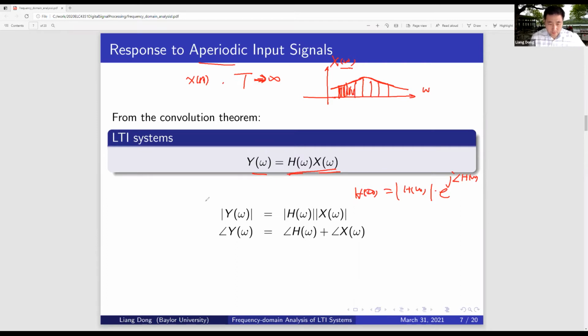So from these two, if I'm trying to find the output signal, what we need to do is take the input signal. Let's say I have a filter. This filter is ideal, and I call the system a filter because it's ideal. This is my H(omega). H(omega) is a bandpass filter, so it's a square wave from frequency F1 to F2. This is the absolute value.